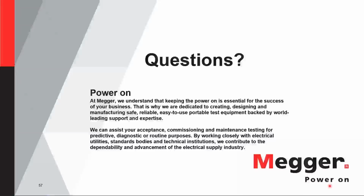Remember that D1816 uses this mushroom type, these round electrodes, which are a closer representation, I should say, of what you find inside a power transformer. Also, D877 will be less sensitive to water and conductive contaminants, especially when testing above 25 kV. Okay, thank you, Daniel.